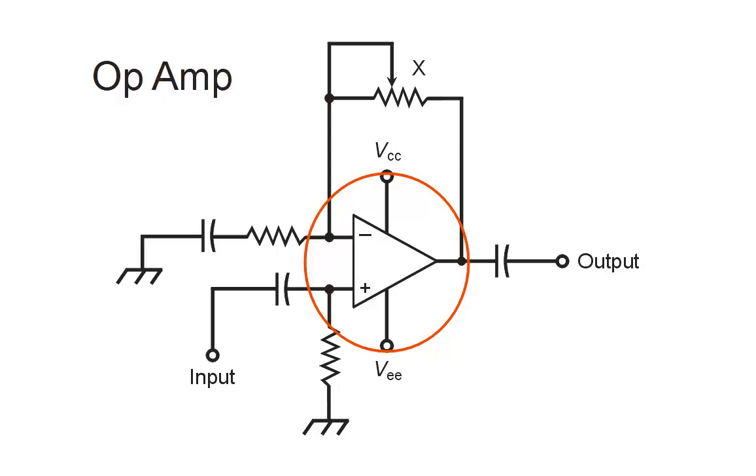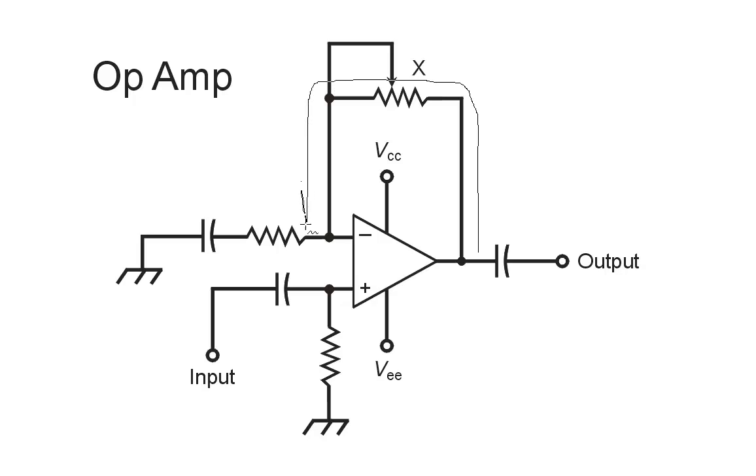And it's connected in a certain circuit to provide an output signal that occurs in phase with the input. The input goes through. That plus sign means the non-inverting input, so the output comes out in phase coincidence. Then we have some feedback taking place from the output through this potentiometer X and back into the inverting input.